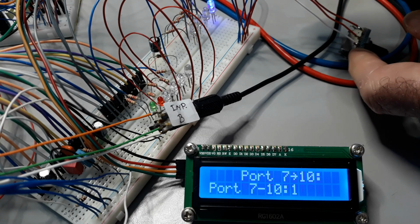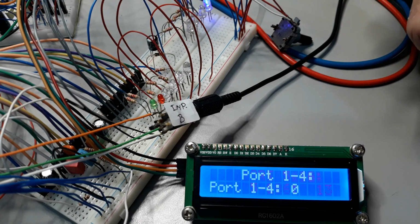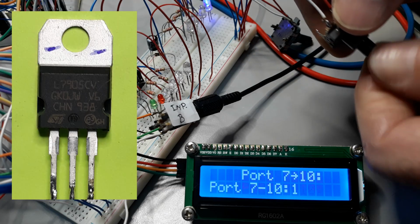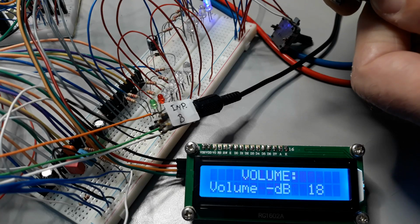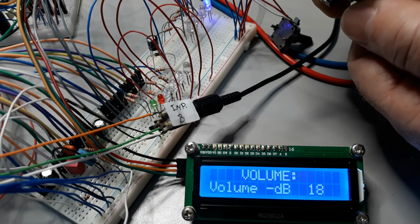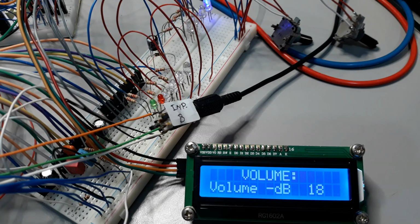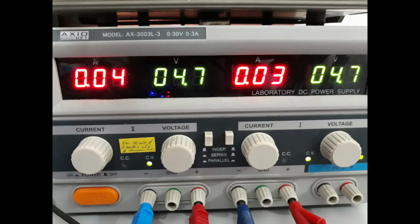To safely handle this requirement, 2 low dropout regulators were used, namely the LM7805 and the LM7905, assisted by 2 transistors. The integrated circuit consumes approximately 20 mA on the positive supply rail and 20 mA on the negative supply rail. The liquid crystal display adds an additional current consumption of roughly 20 mA to the supply.